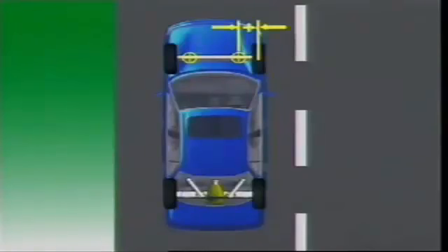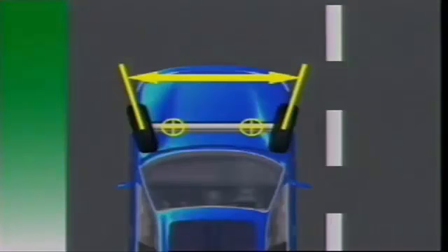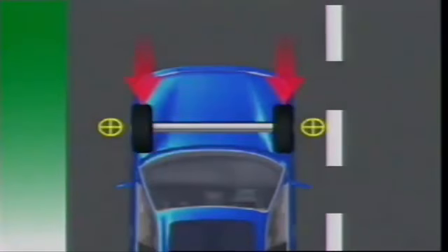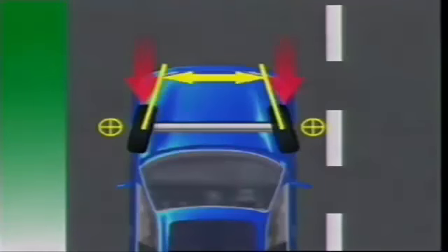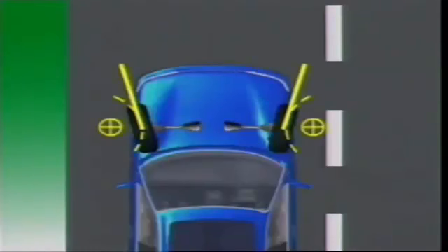On a rear-wheel drive vehicle with positive scrub radius, the vehicle's forward motion and the friction between the tire and the road causes a force which tends to move the front wheels back. This would cause the wheels to toe out. If it has negative scrub radius, the front wheels again tend to move back, but this time they toe in. On front-wheel drive vehicles, the opposite occurs. Positive scrub radius causes toe in, and negative causes toe out.